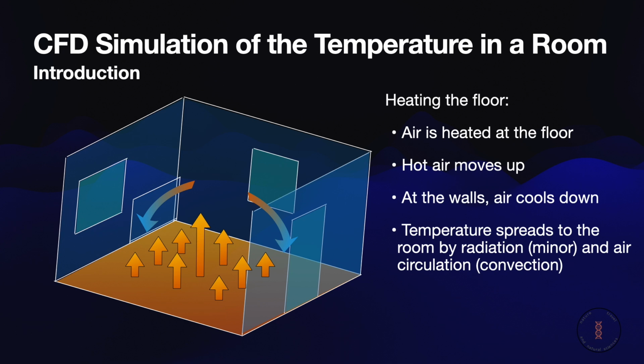For the second scenario, we simulated an underfloor heating system, where the floor serves as a homogeneous heat source. The heat rises uniformly from the ground towards the ceiling. In this case, convection remains the primary driver, but due to the lower surface temperature, the radiative component and the flow profile differ significantly from the wall-mounted unit.